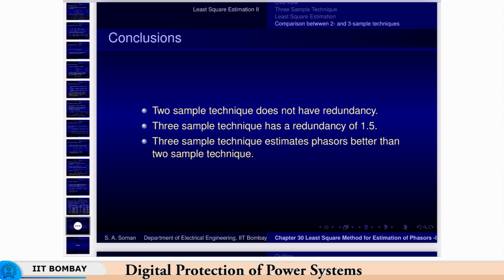So, your computation becomes very simple. Okay. So, as long as the number of samples is more than 2, and then for redundancy more than 3. So, commercially available sampling rates rather will be 12 samples or 16, 20, that range.